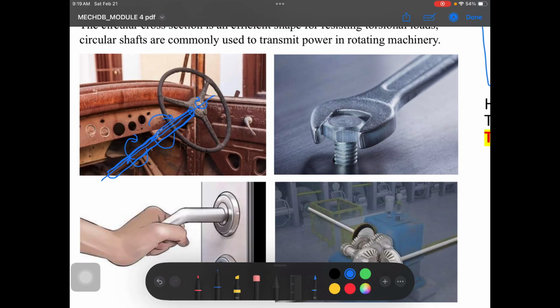Next, here in the bolt, this is the tightening of the bolt. How do we tighten a bolt? Of course, we have a wrench. The wrench holds the bolt here and also holds the other side. This wrench also applies a couple. To twist it, say counterclockwise, the wrench applies a couple force like that. The bolt head twists, so this head receives the couple or the moment. And then, what is the effect of this moment on the shank or body of the bolt?